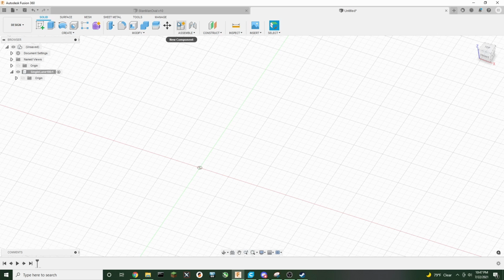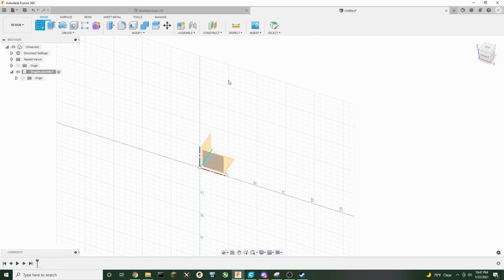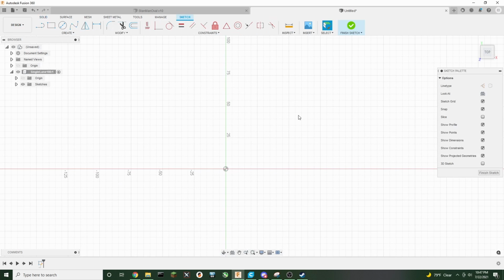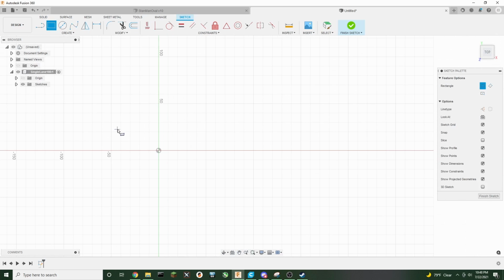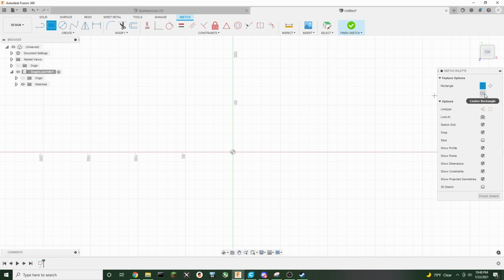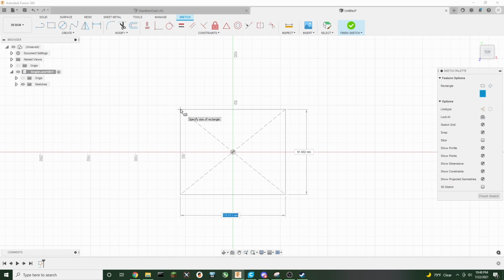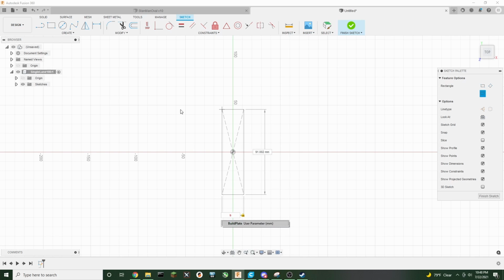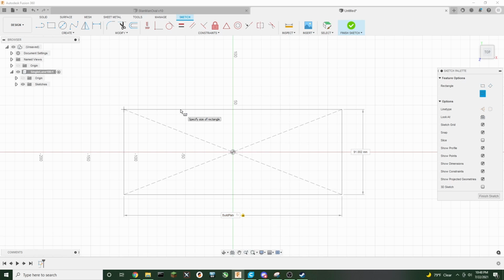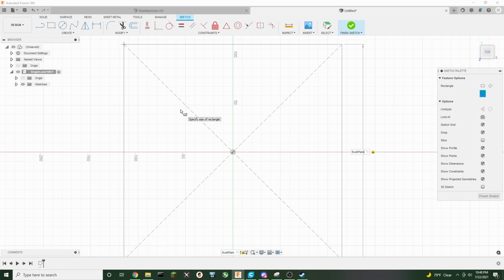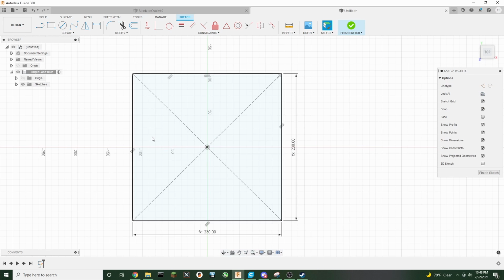So we're going to create a sketch, and we're going to create the sketch on the floor. With this sketch, let's do a middle center rectangle, and we're going to click here in the middle. You can see now that these numbers are actually adjusting. The numbers wouldn't show up previously. I can type anything in here, but we're going to use our build plate. Hit enter, hit tab, go to the next one, and say build plate. Alright, so this is our 3D printer build plate.